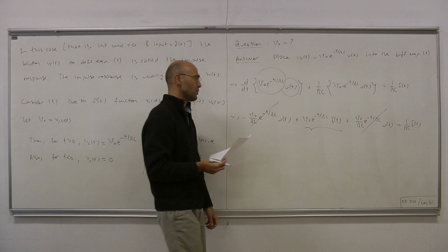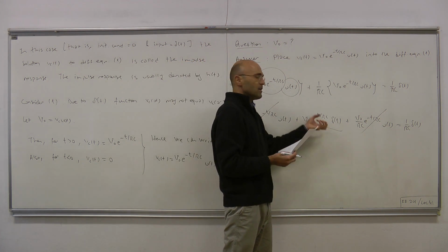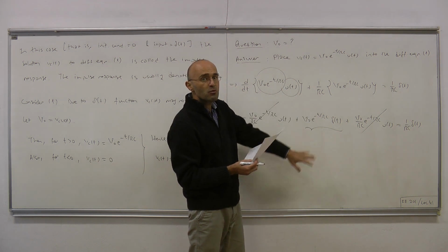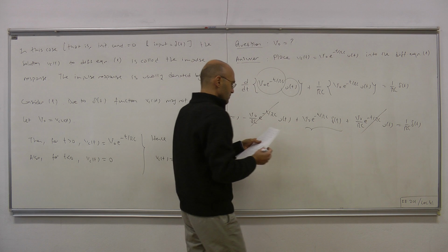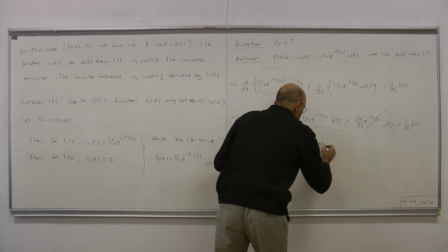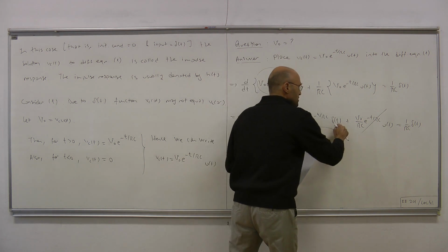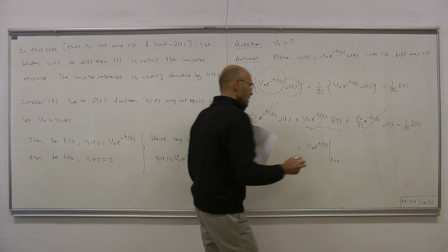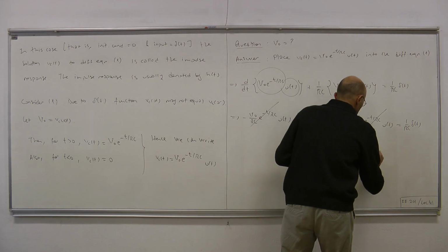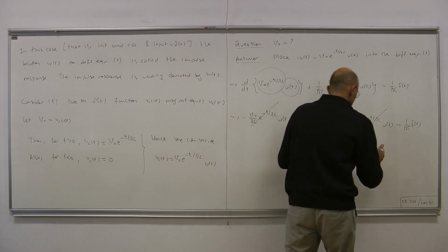In this case, it's t equals 0. We obtain a constant times delta(t). For all practical purposes, we can replace this expression with that. Hence, this equals V0 e to the minus t over RC, evaluated at the point which makes the argument of the impulse 0, times the impulse. Okay, so that should equal 1 over RC delta(t).